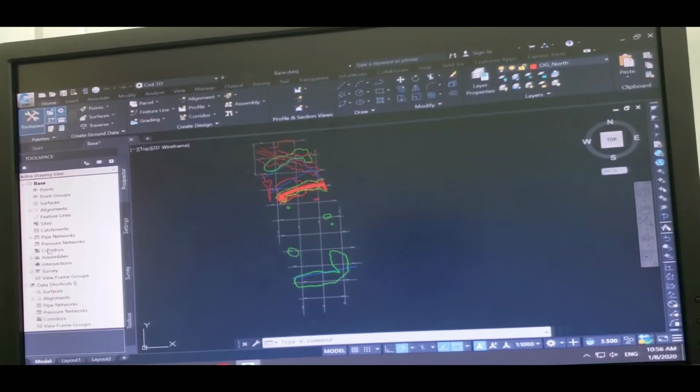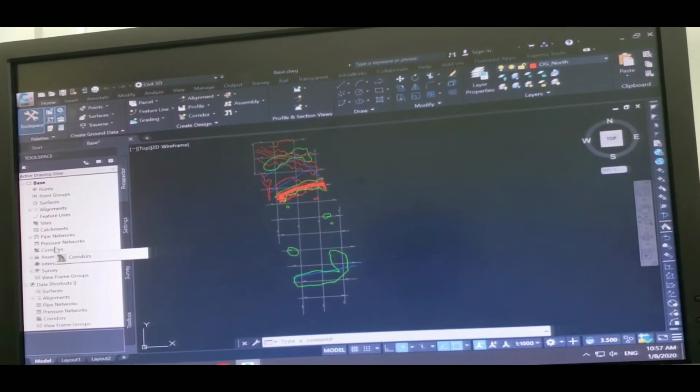And what we're going to be looking at as well are corridors. Pretty much corridors are going to tell us how our road is going to look like. So we're going to tell AutoCAD, okay, this is how the road looks like. We have 2 lanes, each lane has this many meters. We have a sidewalk, we have this type of curve, and AutoCAD will calculate how the road will look like here, okay? You will look into a topic called super elevation on the lecture portion.